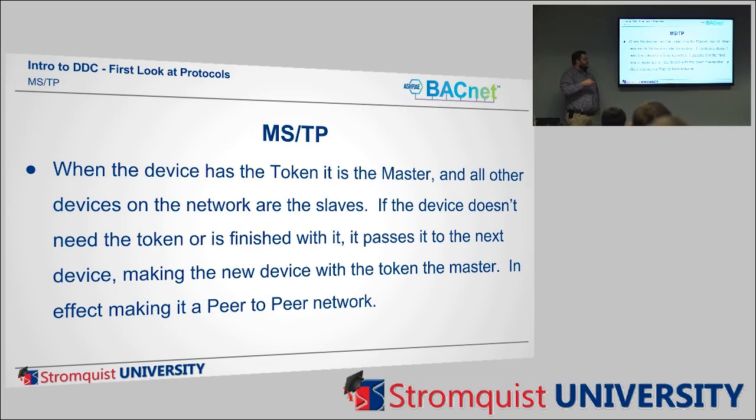So what BACnet did with this is they took traditional 485, which was Modbus or COM4 or N2, which has one master that has to handle all the communication. So if this VAV needs to send data to this VAV, it's got to go through the master. Well, with this technology, the master changes, so when this VAV needs data from here, when it's his turn to be the master, he just goes straight and asks for it. So it's a lot more efficient way, and that's why you have a lot more features in BACnet.